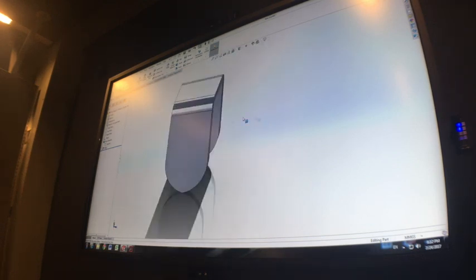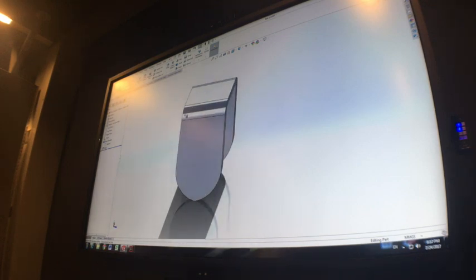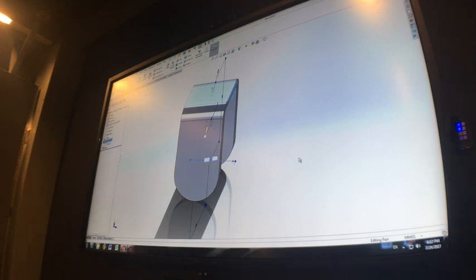The other thing to be aware of, and I'll try and mention this regularly over the next couple of weeks, the idea behind SolidWorks and your 3D modeling is considering your design intent, what you're trying to achieve. If I'm trying to achieve a part which is just going to be one size and it's never going to change, then it's fine to put in that dimension and do that fillet at 12.5. But what happens if later your client comes to you and says that part is actually now going to be 25 by 40?